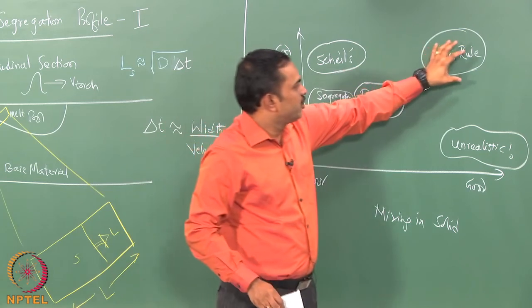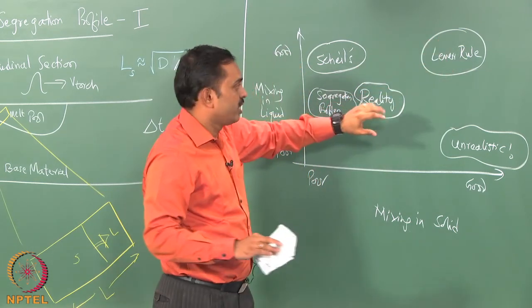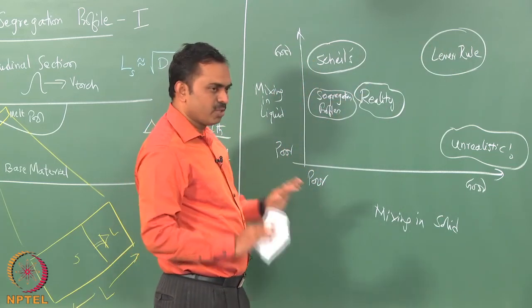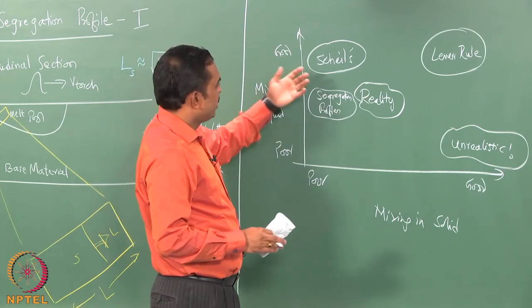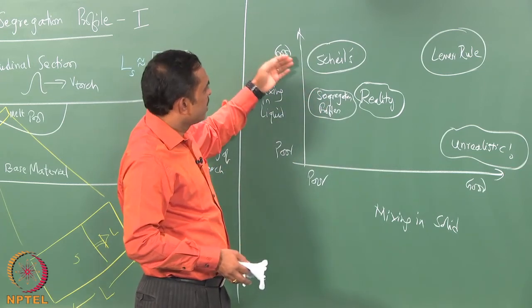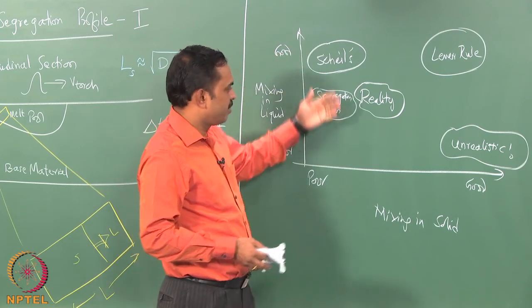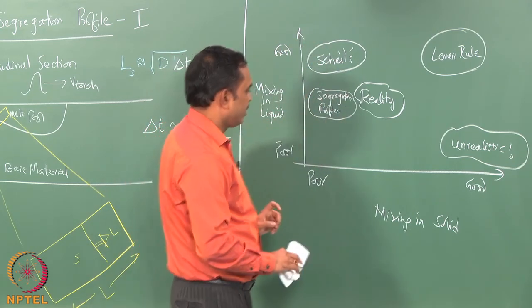and this is the equilibrium situation, extremely slow solidification of welds, maybe submerged arc welds, for example, you may take this kind of situation, and for all practical purposes most of the welds like in plasma arc welding and upwards, you may see that it is quite difficult for the liquid to have enough time to mix. So, you may actually take the Scheil equation regime, and that may be quite realistic, and otherwise you would say that this is the profile that we can use.